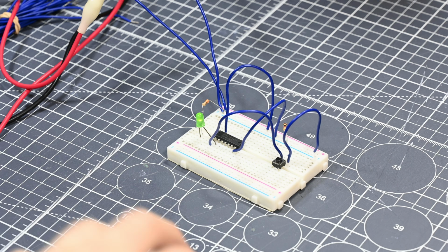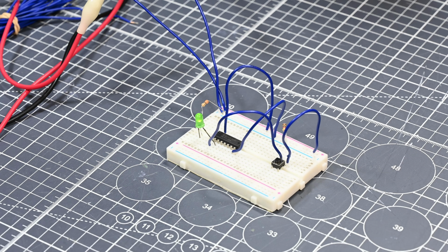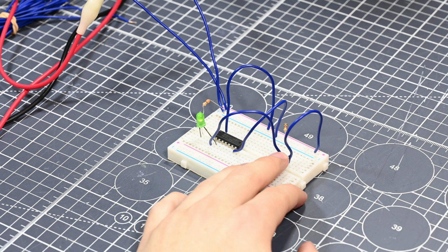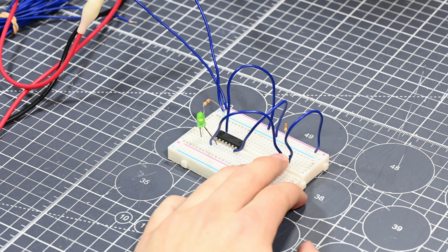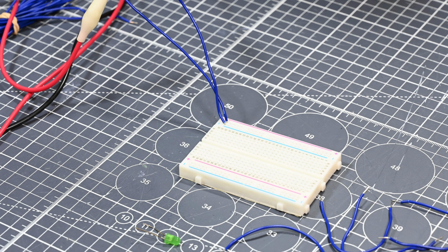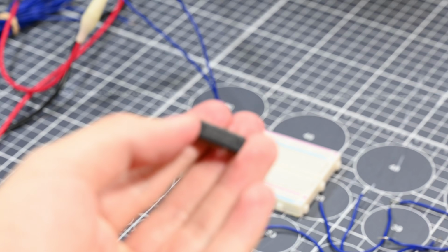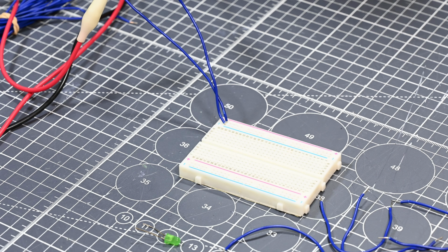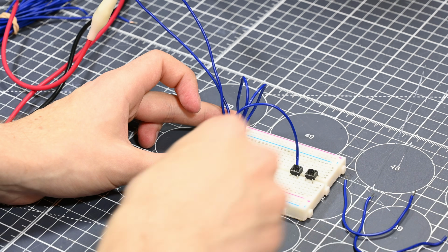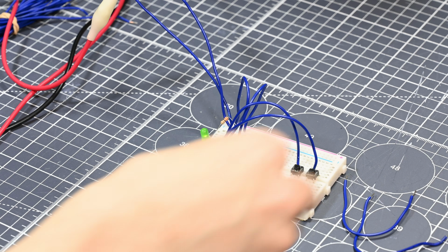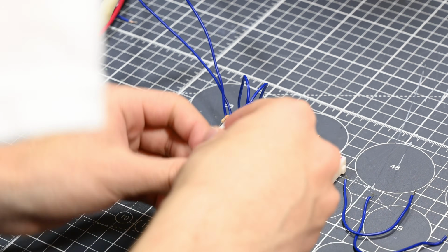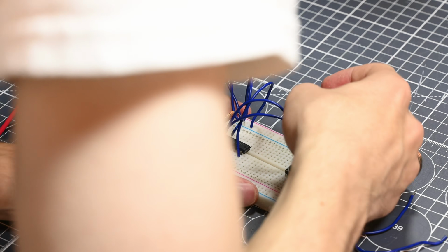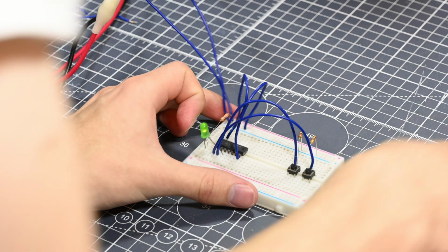Now, I did actually just lie to everyone watching this video, because that actually wasn't the final logic gate IC that I want to show you today, or that I have. I actually have one more, which I really want to show you, the SN74HC132N. This is a quad NAND gate IC, which exhibits its own properties as its own operation, but it also has another trick up its sleeve. The NAND gate is a super versatile gate, which can actually act as any other kind of logic gate when grouping, most of the time, multiple of them together in different configurations.